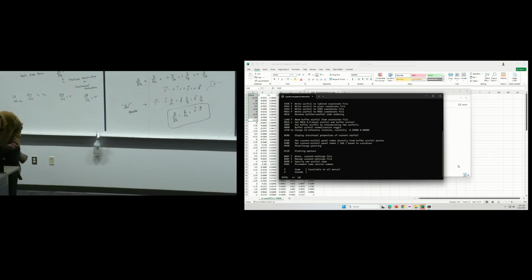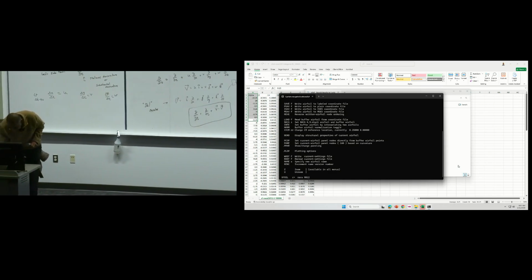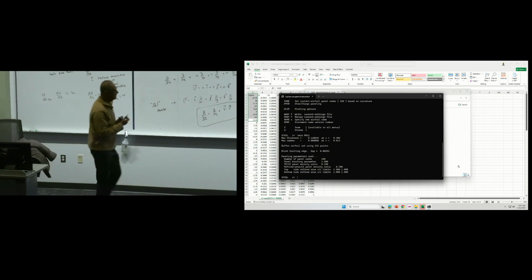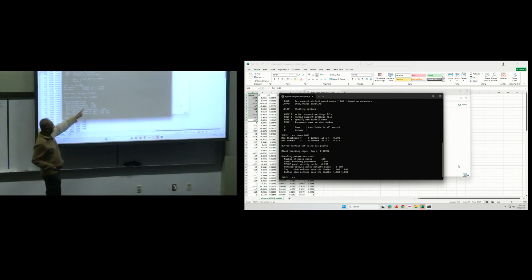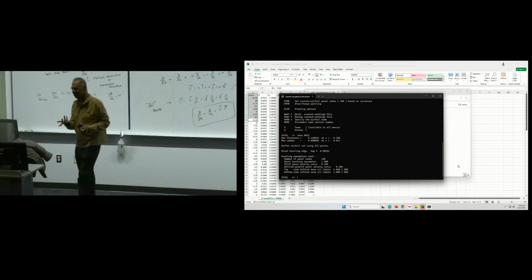So let's say NACA 0012. Basically, it has done 160 points on the airfoil. It's a discrete representation of an airfoil, right? Sometimes near the leading edge region, with such a coarse representation, you may have sharp, ragged edges on the airfoil, okay? Think of a rock. If you define it only with few points, it'll look like sharp edges, right? So the reason at 4 degrees it does not converge is because we have relatively few points.